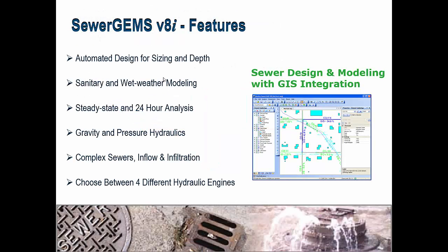Using SewerGEMS, you can automatically design the network for optimal sizing of the pipes and for optimal depth of excavation, that is optimal invert level of the manholes. You can not only use SewerGEMS for sanitary loading, but you can also consider inflows and infiltration under wet weather loading, and then model it and analyze your network for inflows and infiltration.